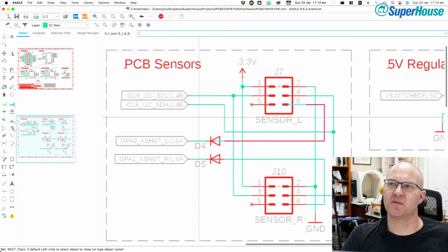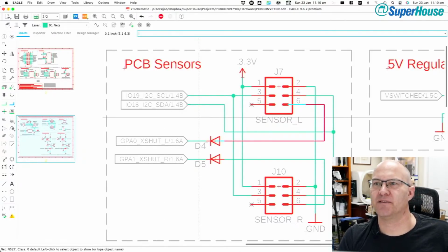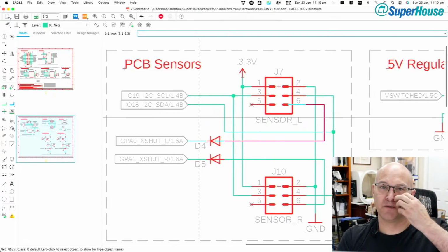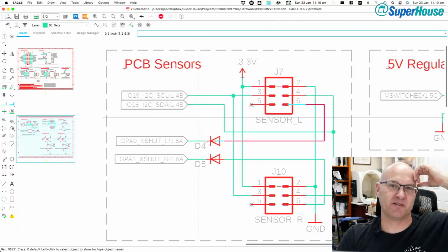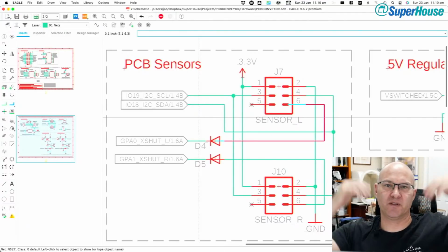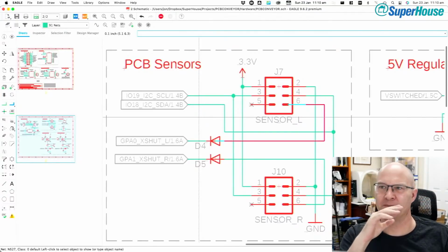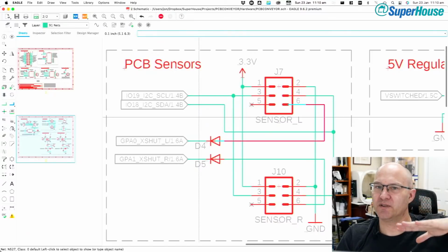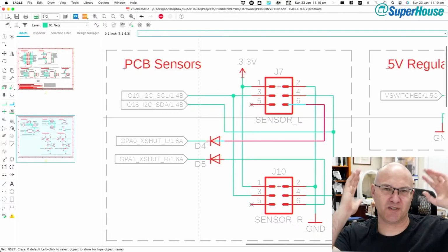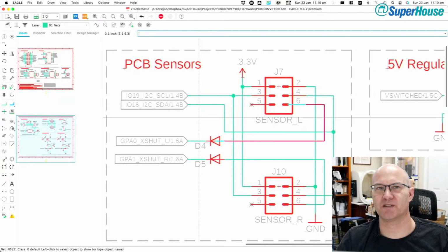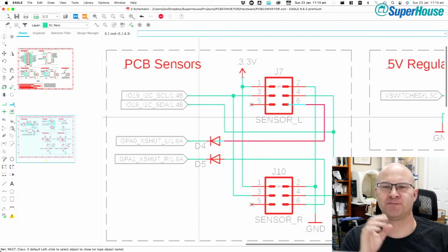Now, these time of flight sensors have a pin on them which is active low. So normally it is pulled high by a resistor, in your circuit or on the breakout, and there's one on the breakout. If you pull that pin low, it puts the sensor into a low power sleep state. So it stops. Basically it's like holding it in reset almost, except that it's not reset, it's different to that. And I'll explain why this is important.